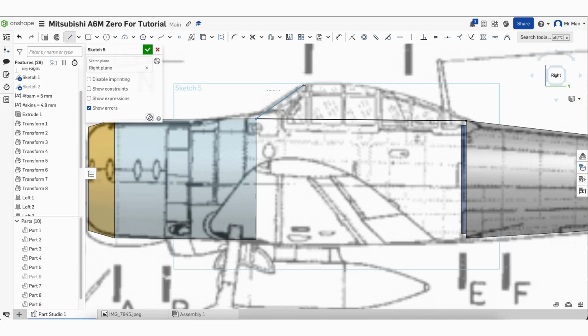And we don't want another line, we're going to do a spline. Now make sure it does not snap horizontal, because otherwise it'll make it hard to make a nice curve. Just leave it a little bit above and we can come back and adjust it. Alright, so now we just move these little dots.